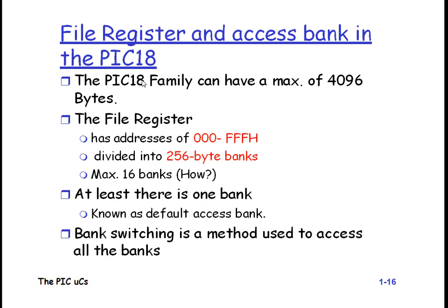PIC register and their SFR bank in the PIC 18. The PIC family has a maximum of 4096 bytes. So the file registers have addresses from this location to this location, and are divided into different banks of 256 bytes, with a maximum of 16 banks.